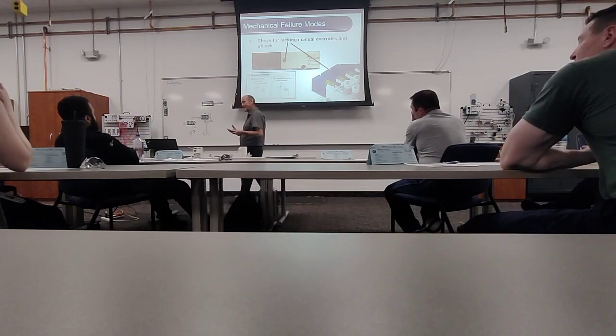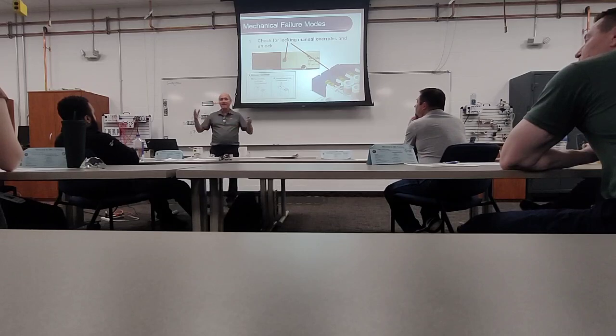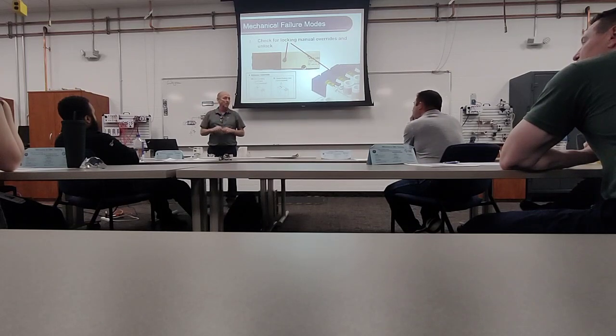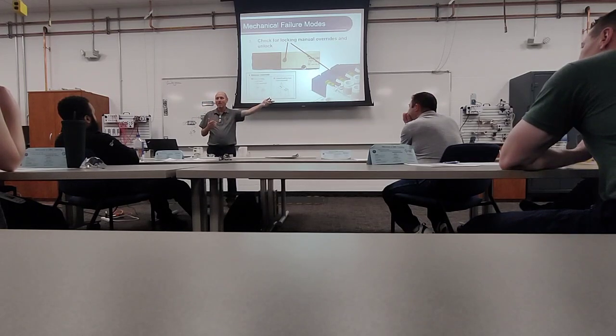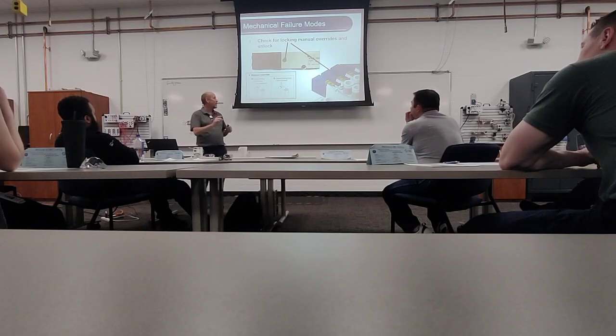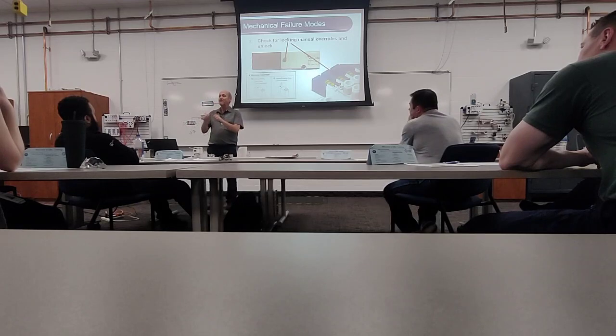Now, the nice thing is when you are building an engine test stand, it's built inside of a bunker, because eventually, when you're testing things, you expect them to do what? Fail. So nobody was hurt, but it was a significant amount of damage and a big setback to that test cell. So again, do not hit an override unless you understand exactly the implications. Now, in your class, if you hit the override, what's gonna happen? You're gonna move the actuator. Now, let me tell you one more thing. Remember I told you you can't bench test a valve?